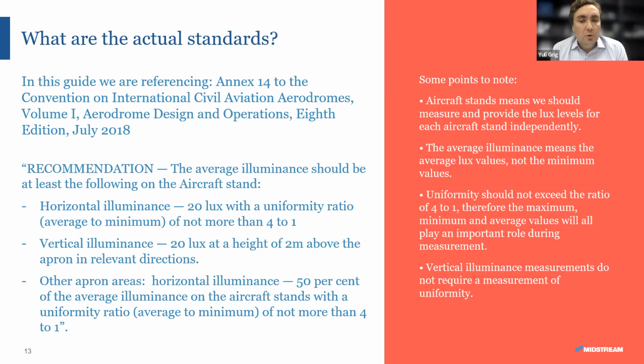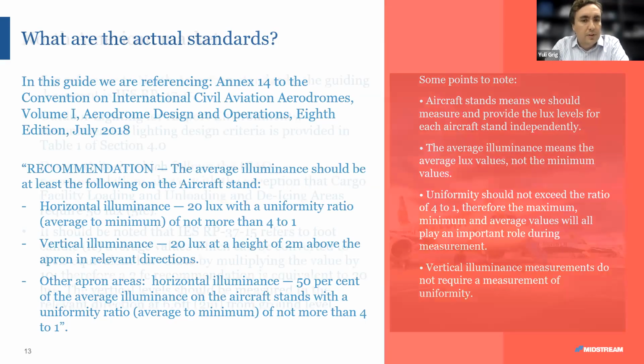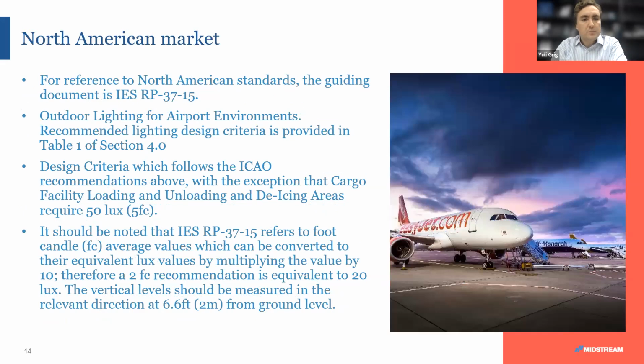And then uniformity should not exceed the ratio of 4:1. Therefore, the maximum, minimum, and the average values all play an important role during this measurement. Okay, so that uniformity can be thrown out if you have a very high level of light in a certain area of the aircraft stand. So hotspots or symmetric optics can cause a problem with uniformity. And again, any questions around that we can tackle further down the line.